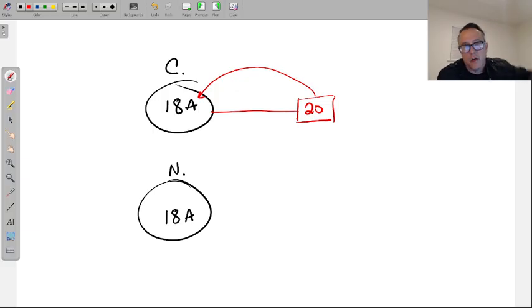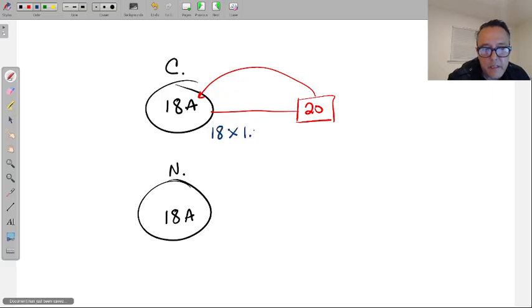Yes, when this thing turns on, it spikes for a second, but remember, this is an inverse time breaker, so it can handle that. What the code is going to tell us, we're not doing this math, but I just want to explain where the continuous is going to come into effect. Just showing the math, and you can feel free to write this out. We're going to have to increase this by 125% first, which I believe is 22.5.